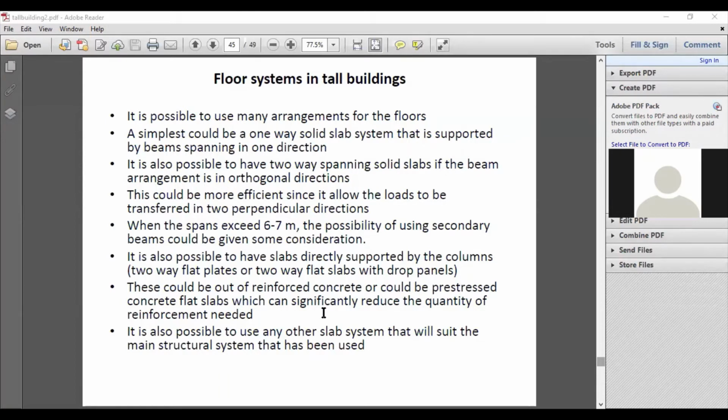So that is a good system where you get steel beams and the decking sheets having a certain shape, and on the decking sheet you will have a thin concrete, and the concrete will behave structurally as a composite material with the decking sheets.